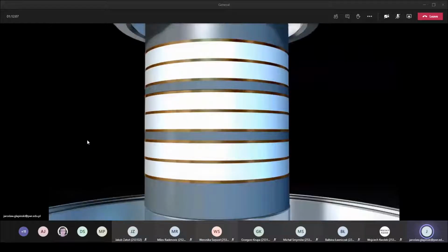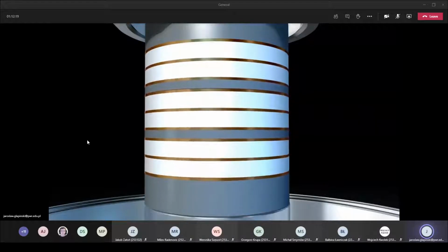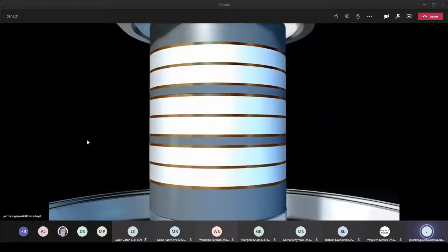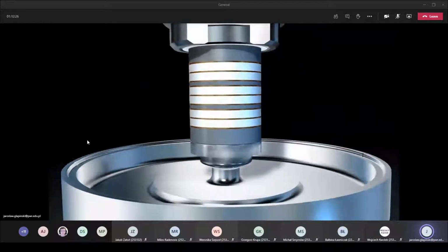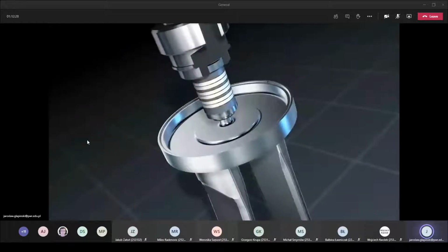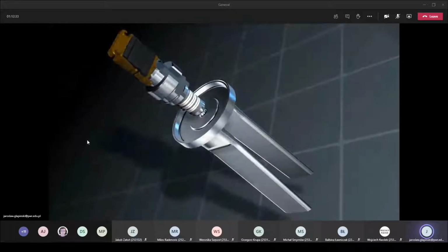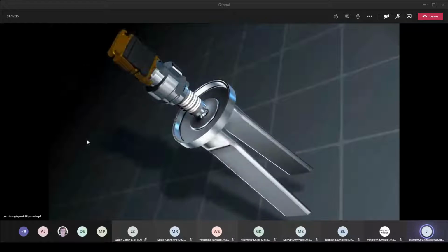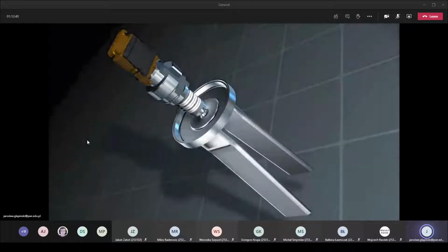The stack drive, however, stacks and fixes several piezo discs with changing polarization on top of each other. The application of a respective alternating voltage also causes the piezos to oscillate. As the piezos expand, the membrane is bent to the outside. The ends of the tuning fork, which is attached to the membrane, are pushed apart. As the piezo contracts again, the membrane is bent to the inside. The ends of the tuning fork, attached to it, are pulled together.